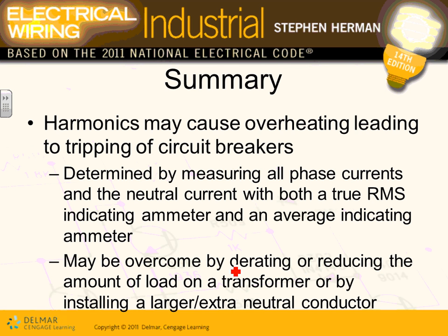These PDUs that you were looking at when we have pictures of PDUs right there, these PDUs have filters in them. They filter certain harmonics based on the equipment. And the filter, guys, goes by frequency. So you can have a filter for 120 hertz and a filter for 180, or a filter that can go multiple frequencies. So that's what they do.